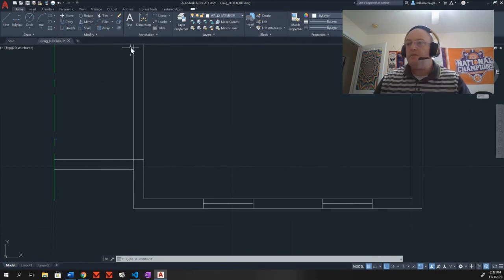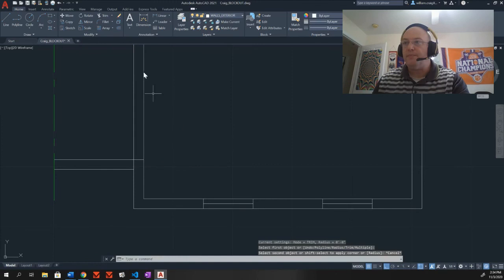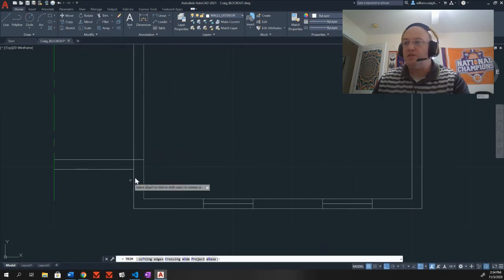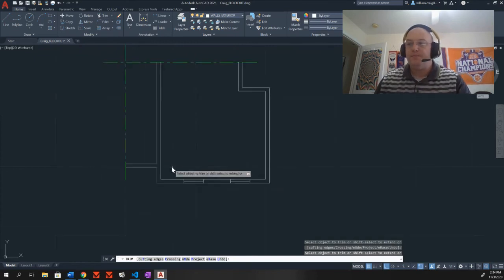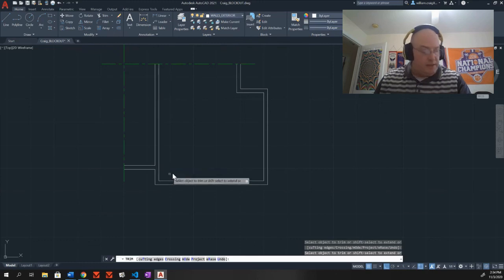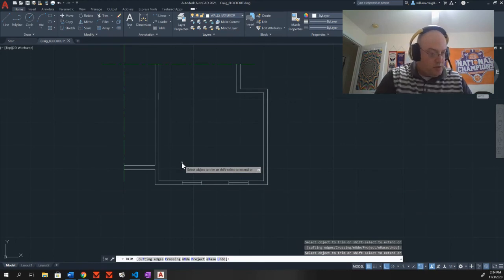And to do that, can I fillet this? No, I cannot use fillet. I have to trim it. Grab the trim tool, make sure you select all these, turn them into trim lines, and then trim out these two little pieces here. You can see what that did there. Perfect. All right. That gets us through step 9. Perfect.